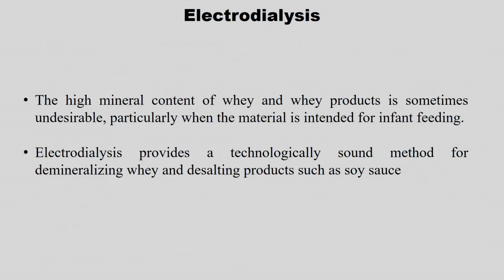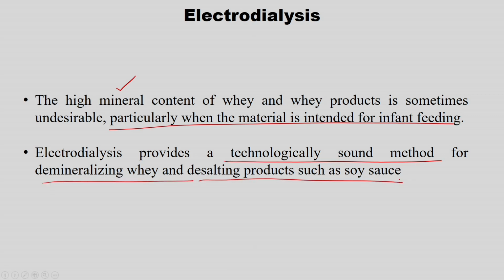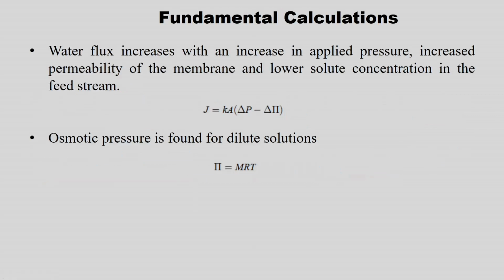And the high mineral content of whey and whey products is sometimes undesirable, particularly when the material is intended for infant feeding. There also, electrodialysis provides a technologically sound method for demineralizing whey and desalting products such as soy sauce. So, in these two applications also electrodialysis is being used.